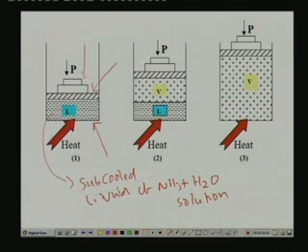Now, let us say that we start heating the system or we start heating the solution by supplying heat to the solution. Okay. Then what happens? You will find that since the initial condition is subcooled liquid, to start with nothing happens. Okay. But as the temperature increases slowly, you find that at a certain point the first vapor bubble forms. Okay. So, if the cylinder is a transparent cylinder, you will observe that the first vapor bubble forms at a particular temperature. Let me call it as T bubble. Okay. So, T bubble is the temperature at which the first vapor bubble forms at a constant pressure.